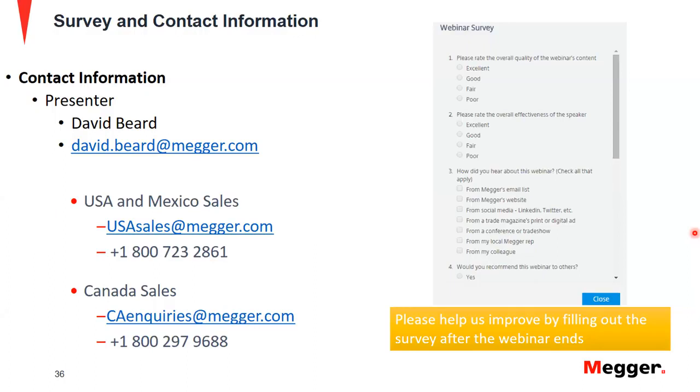I'm assuming David was referring to the curve type in the relay. You can have the same curve type, but if you change the time dial, you can coordinate a downstream and an upstream relay. So having a U3 curve for SEL relays, you can have a time dial 2 for one relay, whereas time dial 3 for the other relay. So you can have some kind of time compensation there.